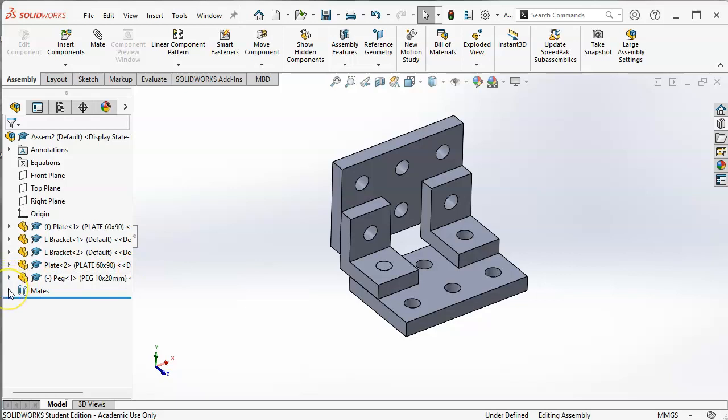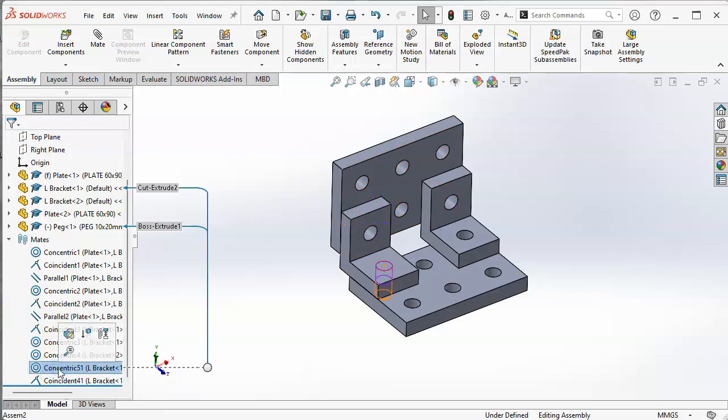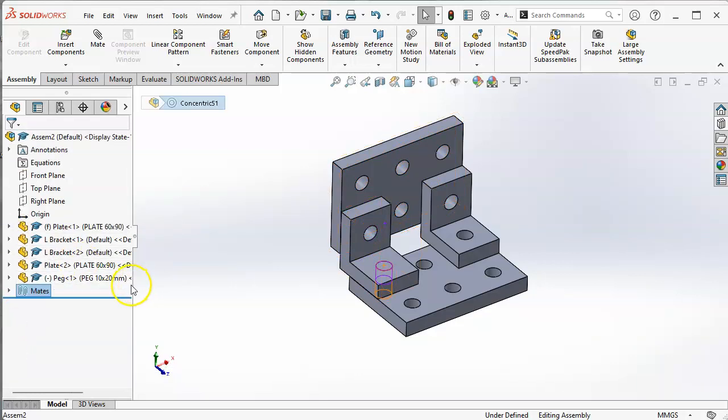Another advantage is that I will be able to go find the concentricity, and this may be one where I want to wait until I've applied all of these. So control button, left click, drag, and then fingers get a little more contortion practice. So I also have to hit the tab button before I let these go. Once I've got this going the right way, at this point I'm holding down the control button with my thumb, I'm operating the tab with my left index finger, and the left mouse button is positioning the item.